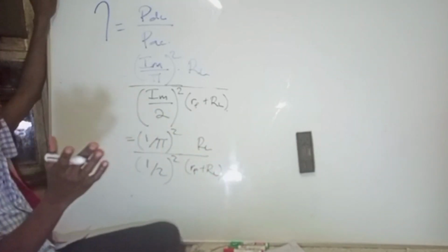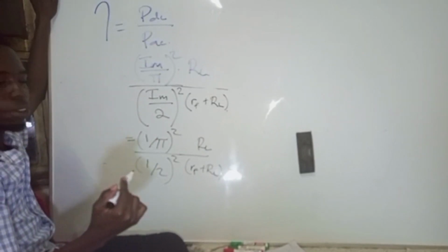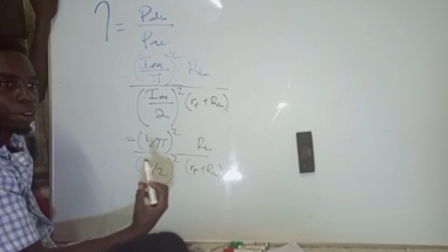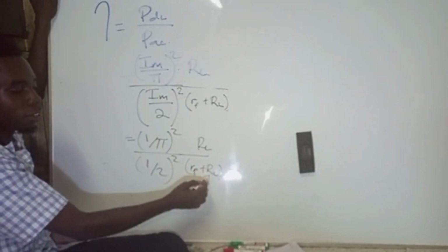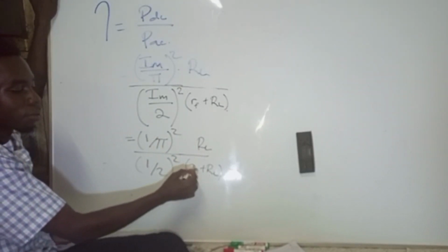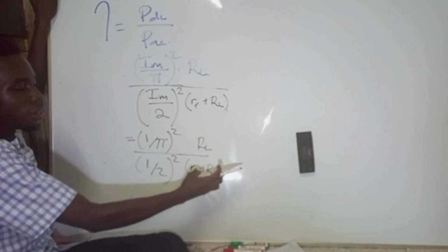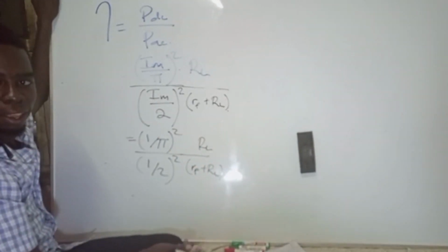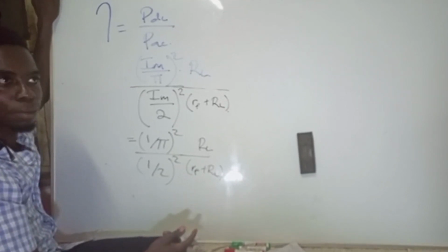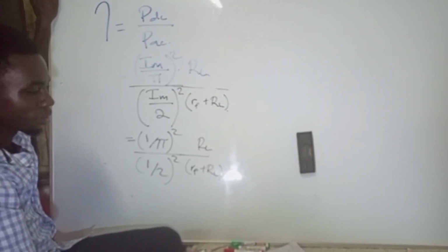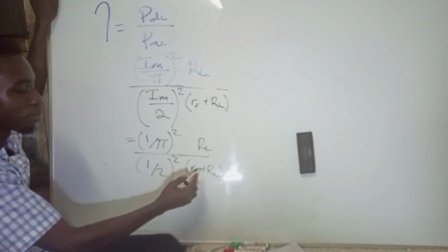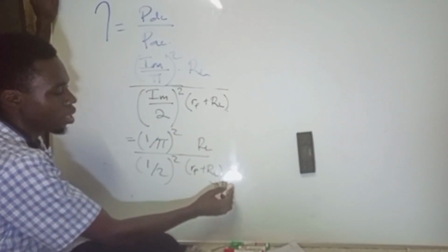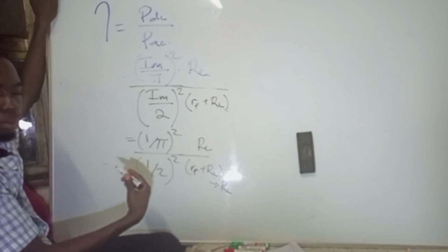Now this is where what I was talking about comes into play. We said this RF plus RL, since this is small and this is big compared to this, will approximately be equal to the bigger value. It's like 1000 plus 1 will simply be equal to 1000. It's like you never added anything. So realize that this will equate to RL, and therefore this and this will cancel.